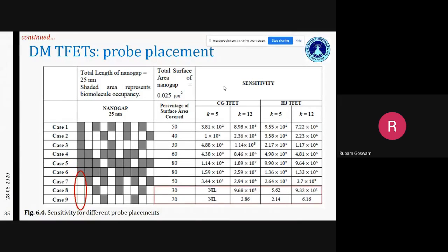Since in TFETs the tunnel junction is the most important area, it is a challenge to concentrate most of the activity around that particular junction. This is an advantage in that the channel can be shrunk down, but also a disadvantage because you have to be very careful about the source doping concentrations and the tunneling width in that region, and about the steepness of the profiles in your junction. So everything comes with a boon as well as a bane. That is the case for TFETs.